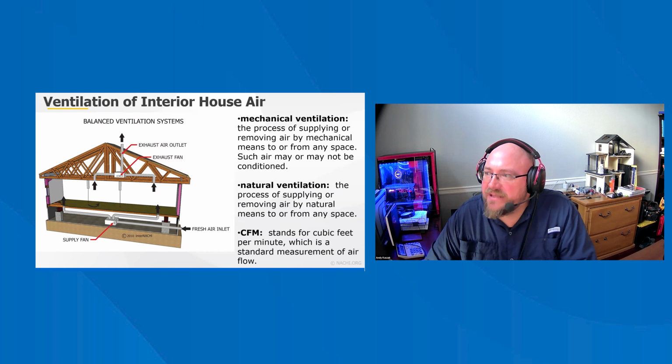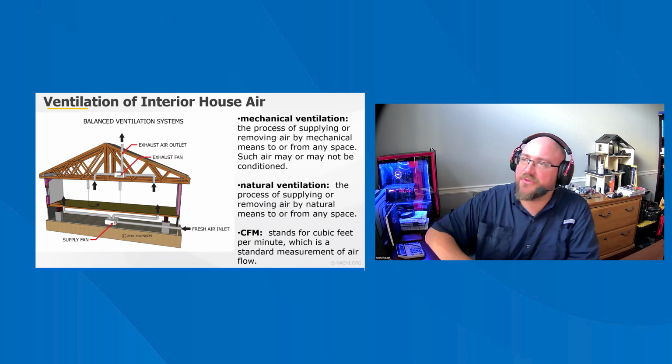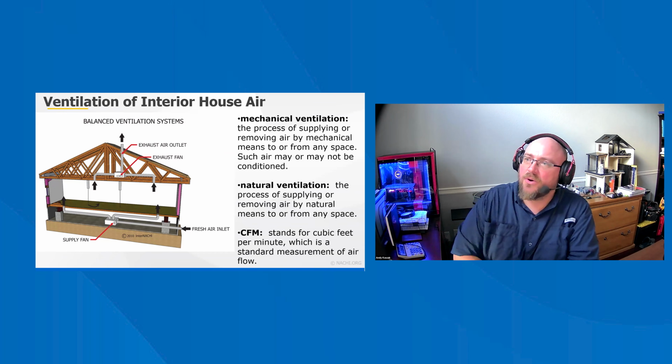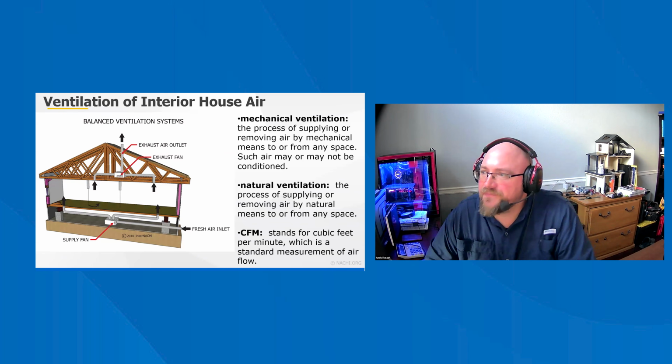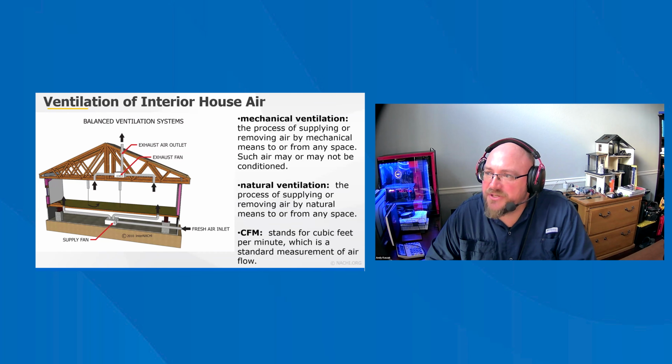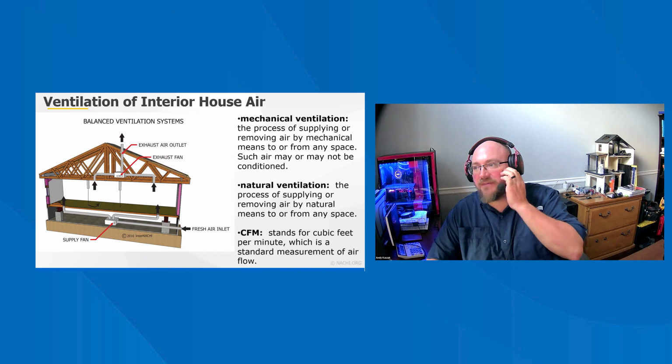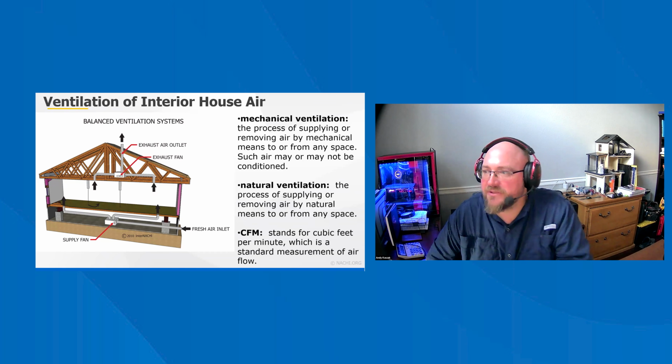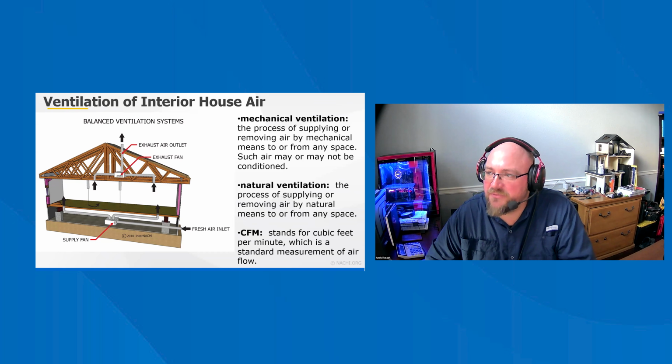A home can be ventilated in the following three ways. Natural ventilation is uncontrolled air movement through the home, into a home through cracks, holes, windows, and doors. This method cannot be relied upon for tightly sealed and many new construction homes. Whole house ventilation is controlled air movement using one or more fans and duct systems. Spot ventilation is controlled air movement using localized exhaust fans to quickly remove pollutants and moisture at their source. It is typically used in conjunction with one of the other strategies.